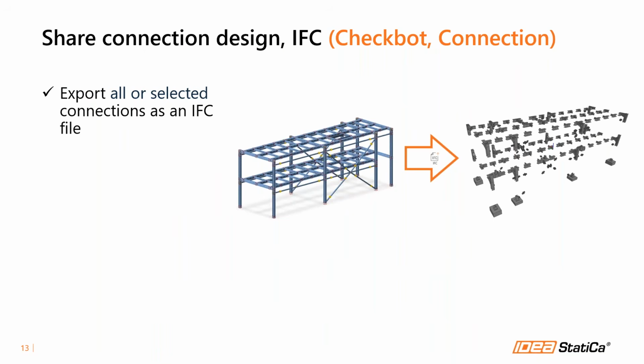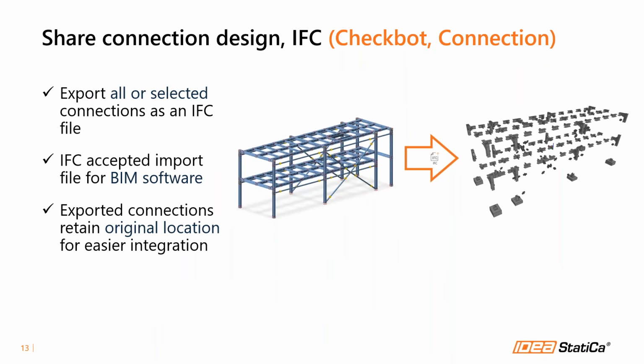We know that writing comments and printing PDFs works, but sometimes it might be tedious, sometimes it might be error prone. That's why we have implemented the option of creating an IFC file in both Checkbot and connection apps. So you can export either all or selected connections and save them as an IFC file. This file can then be used as a reference model in your CAD software, like for example, Tekla.